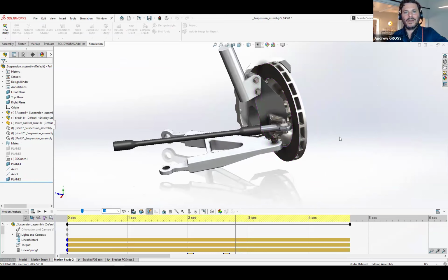So you keep zooming out from the part until you can have tangible information and then build a study around that. And then you can back out reaction forces from motion. Honestly, it's one of the coolest applications for motion: being able to understand your free body force environment without actually knowing it from empirical testing.